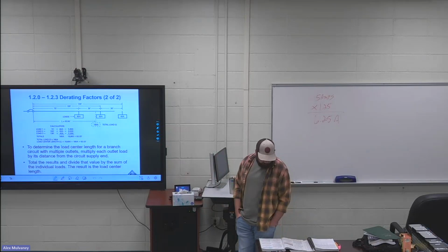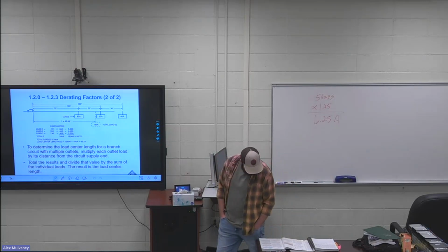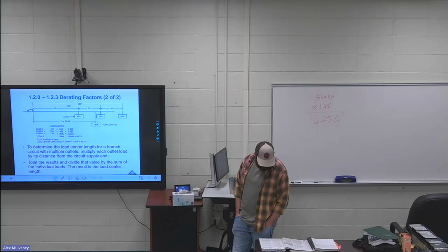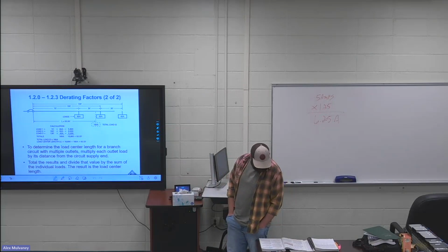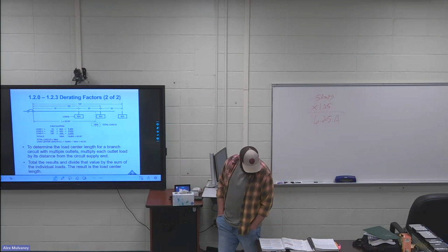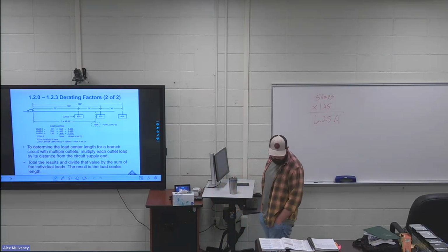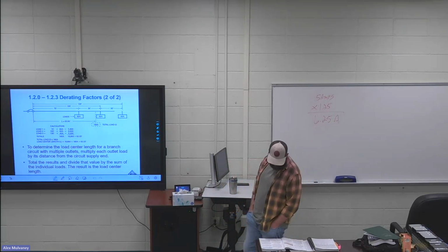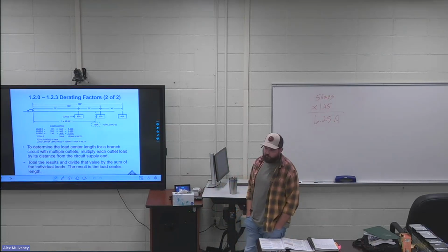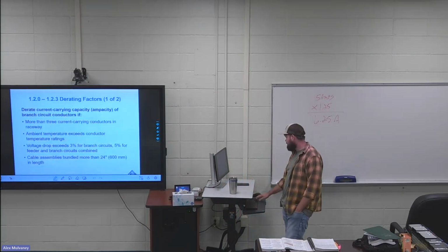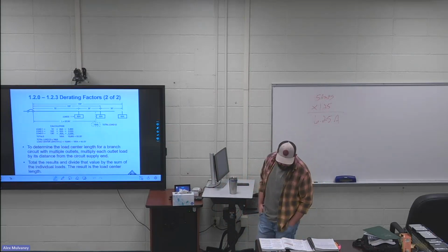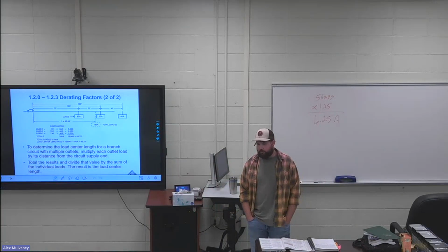The voltage drop for a balanced 3-phase circuits with negligible resistance and power factor of 1 can be calculated using the 2 formulas above by substituting square root of 3 or 1.732 for the value of 2 in the formula. So this is for 3-phase circuits. Instead of using that 2 times, you're using the square root of 3 times.